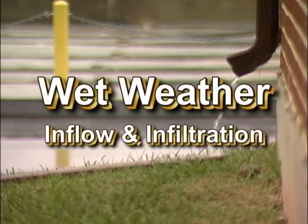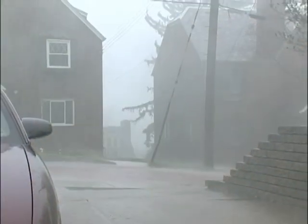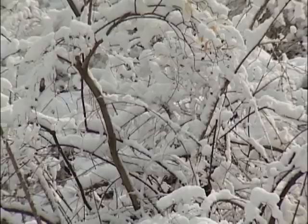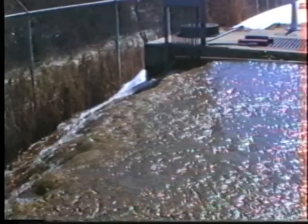Factor number 9, wet weather operations. Many treatment plants in the northeastern United States experience problems with inflow and infiltration into their systems. This extra water enters the systems during wet weather events or snow melt-offs, oftentimes inundating the treatment plant with unwanted water. This often results in the lowering of the temperature and a washout of biological solids from the treatment system. A heavy washout of solids can easily lead to a loss of nitrification.